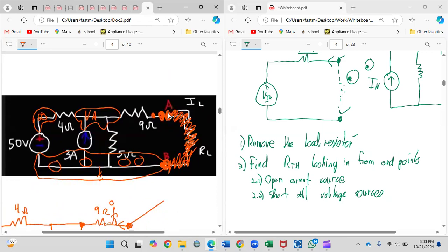Okay, so now what we have to do is get the equation for VA and solve. I think I have enough space on top, so I'll do it here. Same as before, assume a direction for your nodal analysis. I'm going to assume it to be going outwards; whichever one you choose, it doesn't matter. So if I start in here, it's where I'm coming from, minus where I'm going, divided by the resistor in between, plus down here is a current source.